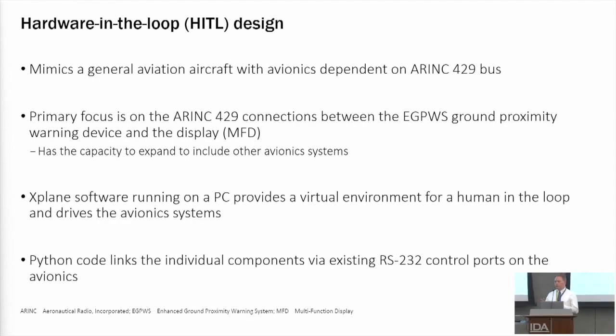We really wanted to create a proof of concept for what we're doing. Even though we're focusing on this EGPWS to MFD connection, I want to highlight that the attack that we want to demonstrate today can be extended to other avionics systems, as Steve was highlighting before. So in order to generate an environment that the pilot can interact with and that can actually drive all the other avionics components, we use the X-Plane software running on a PC. And then we also have generated the necessary Python code in order to allow all of the environment that's generated from X-Plane to propagate out to the various avionics hardware components.